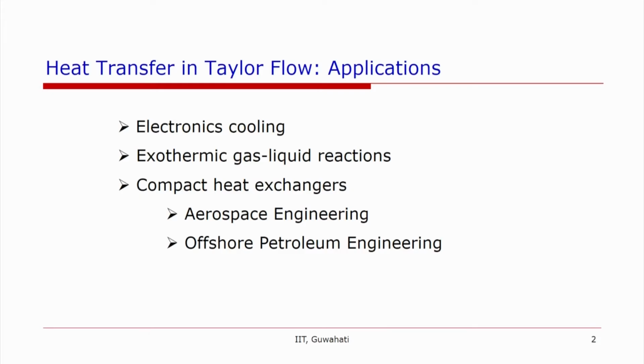Hello. So in this lecture we will be talking about heat transfer in the Taylor flow regime. As we know, in microchannels the surface area to volume ratio, that is surface area density, is large when you compare with large diameter channels or conventional channels.